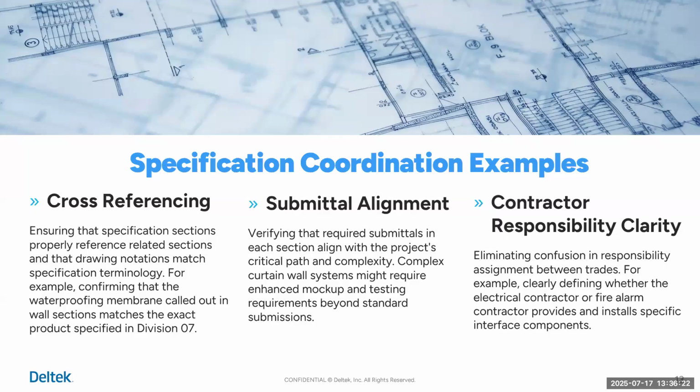But as soon as you put those words anywhere on the drawing, I implore you to go to the spec writer, make your list of those "See specs" notations, and make sure that they are aware of them so that they can pick those up in the specs.